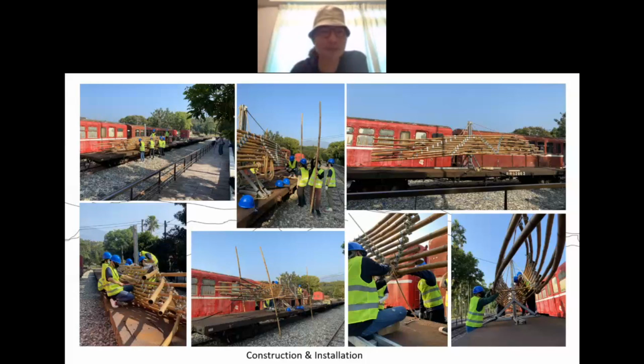In the beginning, we saw maybe 20% or 30% of the clamps going to be loose because the transportation is shaky, especially going up to the mountain. And in the end, I think we only picked up maybe 4 to 5 scaffolding clamps that needed to be fastened out of about 100 clamps. So really, the pre-bend of the bamboo gives it a strength to hold the clamps all together.